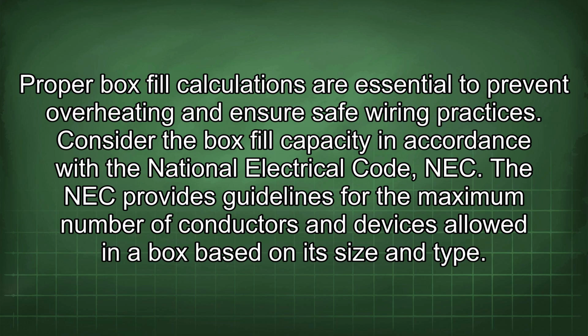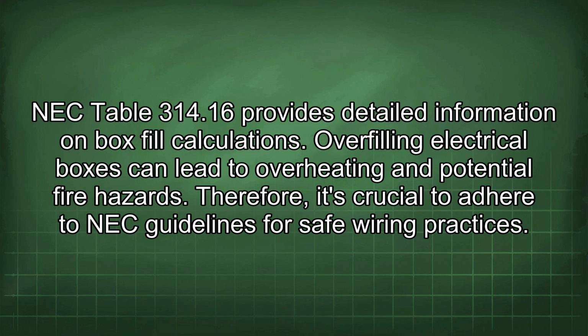The NEC provides guidelines for the maximum number of conductors and devices allowed in a box based on its size and type. NEC Table 314.16 provides detailed information on box fill calculations. Overfilling electrical boxes can lead to overheating and potential fire hazards. Therefore, it's crucial to adhere to NEC guidelines for safe wiring practices.